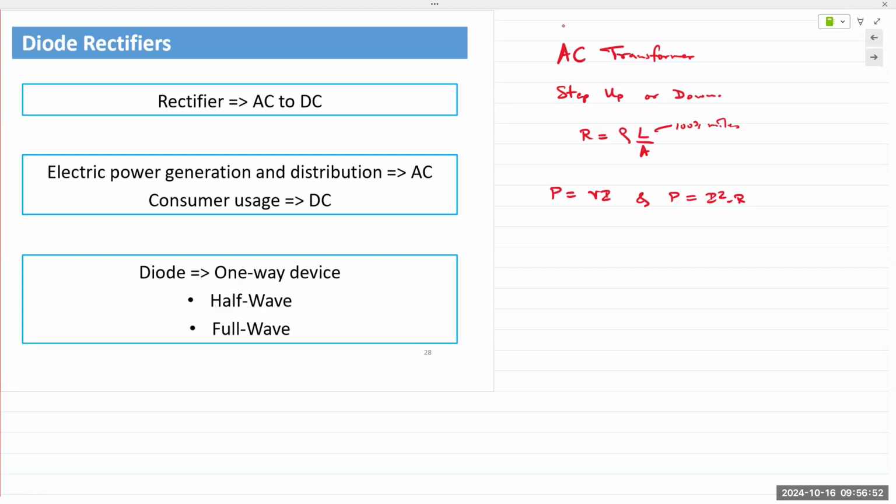So you can either increase the voltage or you increase the current. But if you increase the current, then your power loss is the square of the current. So a huge amount of losses. So it is easier by far to increase the voltage when you send it over long distances. It is very easy to do so with transformers.